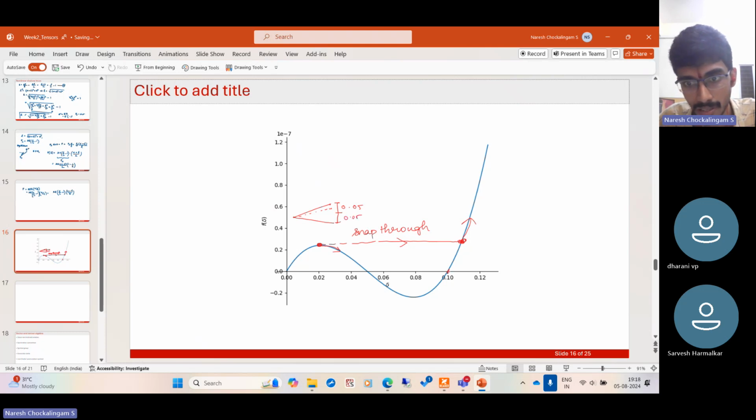So with zero force, if you take it to the critical point and just touch it and leave it, it will just snap to the other configuration with no force. And with further loading, it will just continue in the direction of loading. So this phenomenon is called snap through, and it's a simple demonstration with our truss example. And this is a geometrically nonlinear phenomenon.